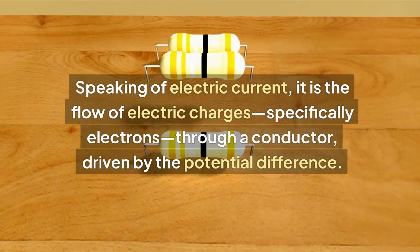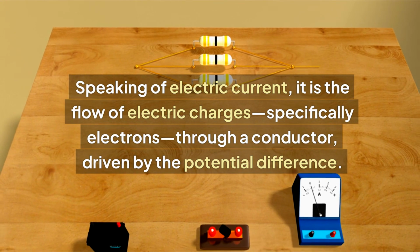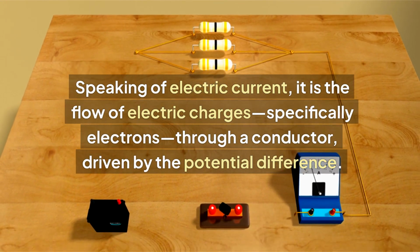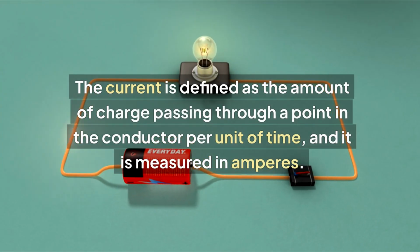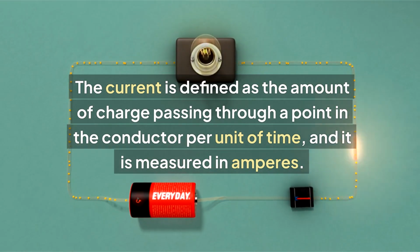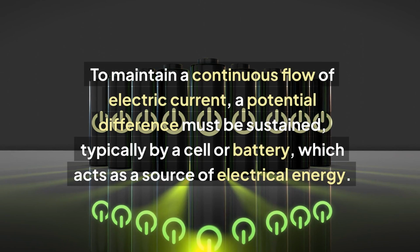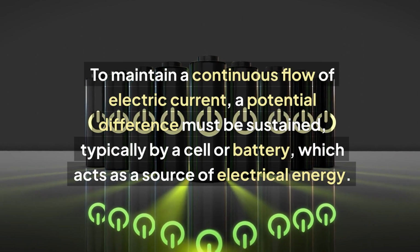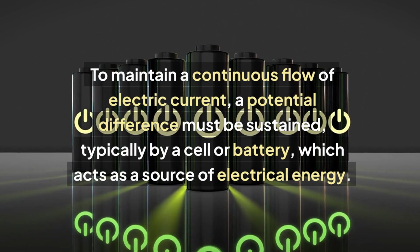Speaking of electric current, it is the flow of electric charges, specifically electrons, through a conductor, driven by the potential difference. The current is defined as the amount of charge passing through a point in the conductor per unit of time, and it is measured in amperes. To maintain a continuous flow of electric current, a potential difference must be sustained, typically by a cell or battery, which acts as a source of electrical energy.